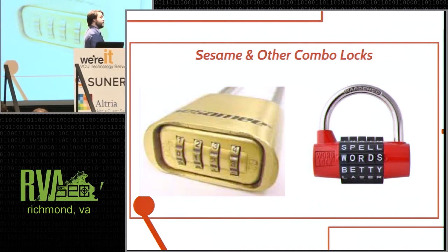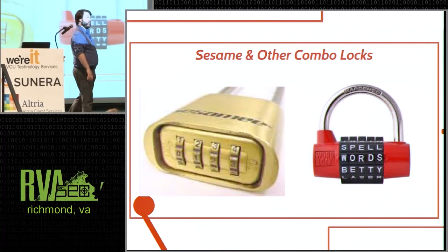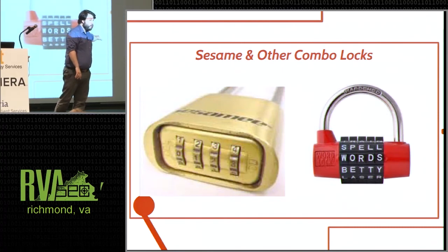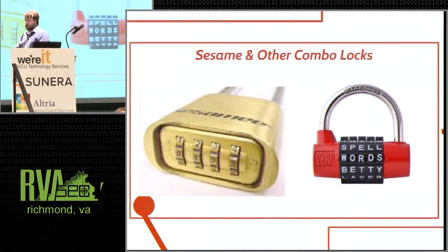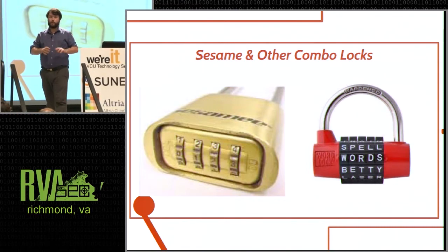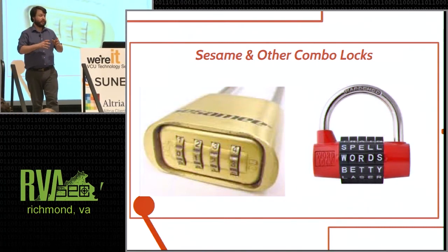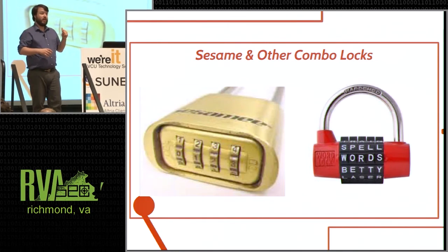In particular, each of these work by having a gap cut out of some portion of the wheel or some other wheel that they're attached to. If you can find that gap, we know that in every combination lock that operates like this, all of those gates in their final position will be in perfect alignment.